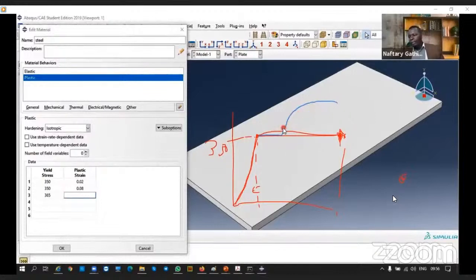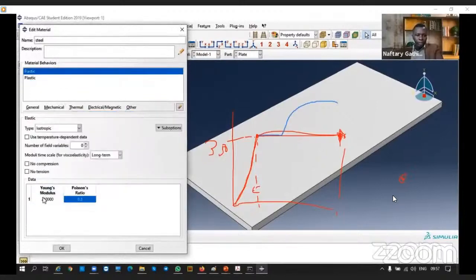For our analysis here, we do not have experimental data. So assuming you can assume a reasonable yield stress and yield strain, and I mean, not yield stress actually, because it will continue, it's not going to yield, right? So it's going to obey Hooke's law indefinitely for my analysis here. So in this case, I just need to define the elastic material. This plastic part I can disregard, I just need to delete that. I just need to define the elastic material, the one I defined, and I say, okay, this material is steel.